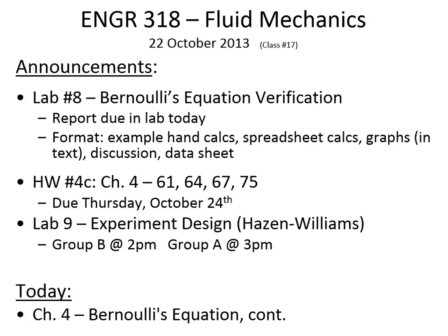So V squared divided by 2g gives you the velocity head term. So your actual measured piezometer elevation of the water plus the velocity head. Now when you graph the energy grade line, it should be above the hydraulic grade line because it's going to be the hydraulic grade line plus the velocity head.